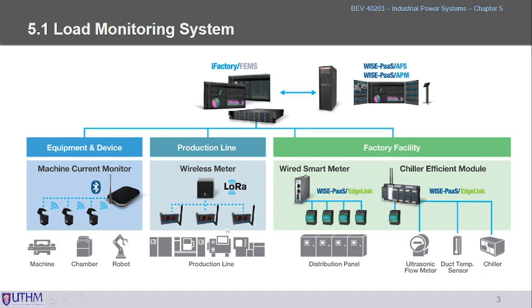In the production line, for example, we have a series of production line equipment and devices, including the fridge. Sometimes we have the fridge, we have the heater, we have the conveyor systems, etc. All these we are going to monitor for the voltage, the frequency, and the currents as well. All in all, here we can monitor the power flow as well. For example, what is the power flow at section 1, for example. In section 2, what will be the Q, the reactive power flow.